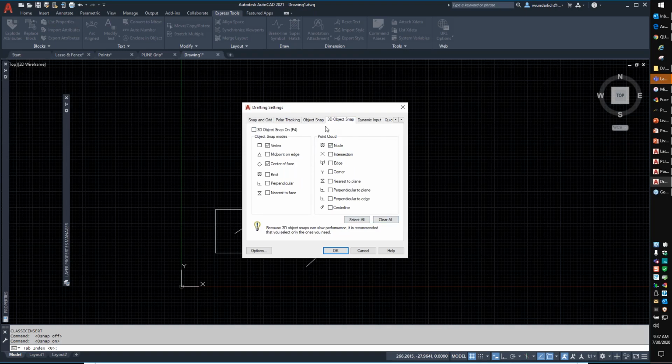The reality is point clouds are nothing more than a fancy XREF that has data points in it. There's not a whole lot you can do to manipulate them. Actually, you can't manipulate the point clouds directly in AutoCAD. They essentially behave and act as an XREF, so you can't really modify anything on the point cloud. That's something you'd need a program called Recap, or one of the other programs out there for point cloud editing. But this will allow you to snap between nodes. Again, your 3D snap is on. I can bring in a point cloud and draw lines between those points with the node on, because it does pick up all of those as nodes. Hopefully that gets you in the ballpark.